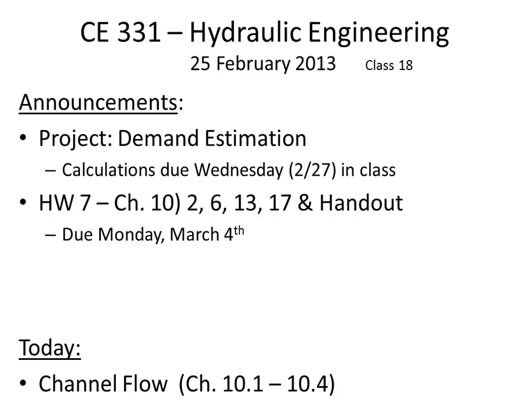You may end up using different peaking factors than me. I think I used 3.25 for the maximum hour and 1.8 for the maximum day. That's based on some other information from a different book, but here it would say that the peak hour is maybe 2.7, and you'll have to do the average to find the max day. I'm not going to eyeball it, but any questions that you want to ask about the project before we get into talking about channel flow today?